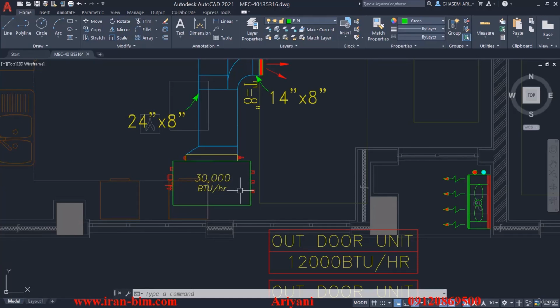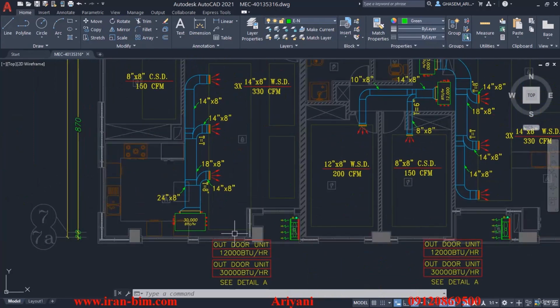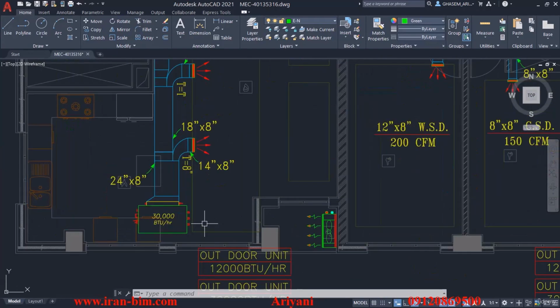And if you actually don't know who they are, and you're trying to think how to model the equipment from the renderings of the 5 biggest companies that you can see, it is usually recommended to select a rendering of the equipment with the biggest size. If you do this and later see a change in your vendor and need to make any changes, you'll have fewer problems. For example, if you're going to model this fan coil over here, you're either going to select the biggest size or the one that's used in the most plans for this type of design.